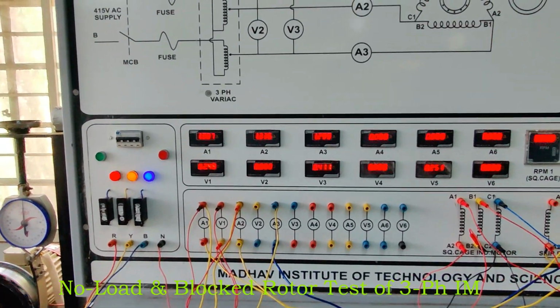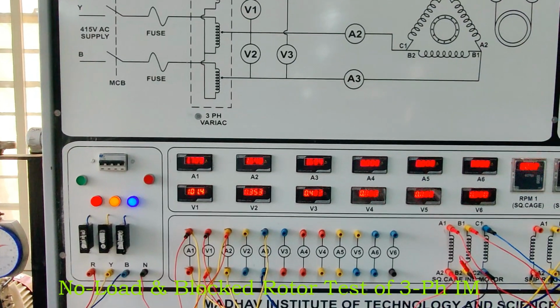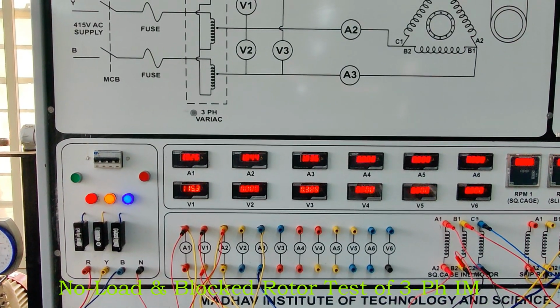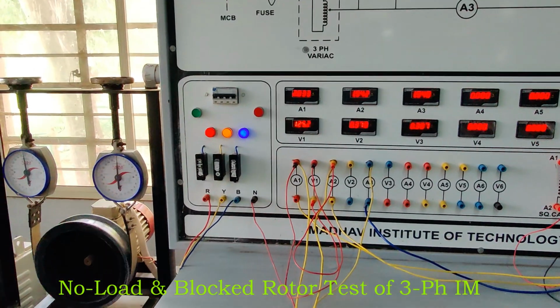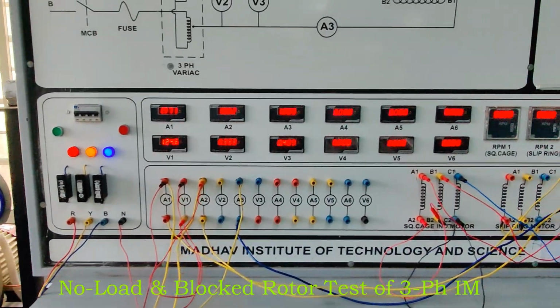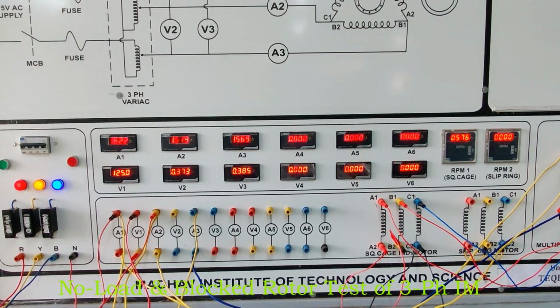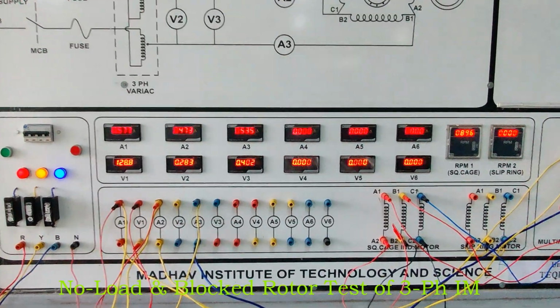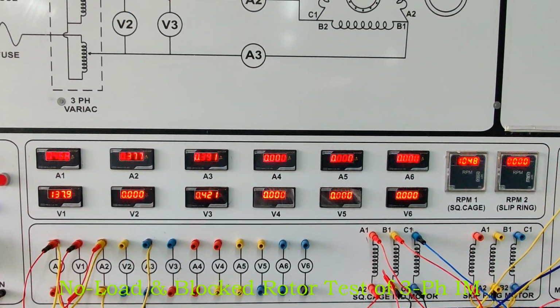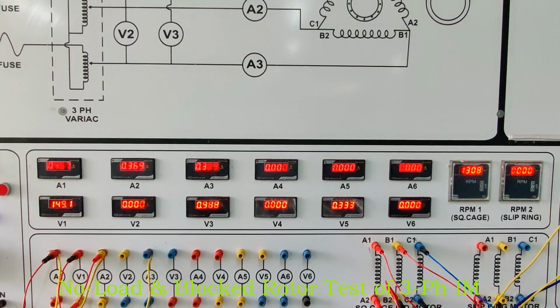As we increase the voltage, the motor starts moving. The speed reaches about 1500, and A1, A2, A3 indicate the line current. See that all the currents are approximately equal. It means the system is balanced.